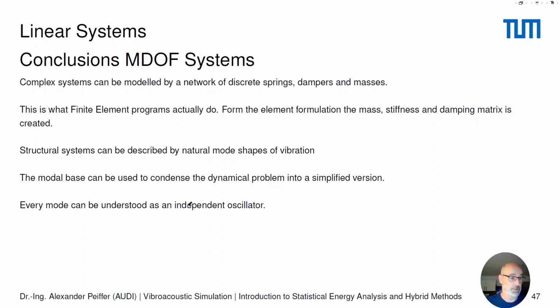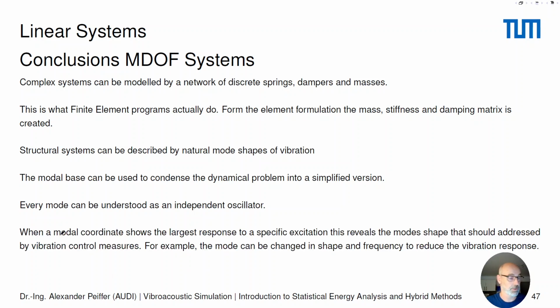Every mode can be understood as an independent oscillator. And what is also important, a hint for practical things: if you look at a problem in modal coordinates and you see that one specific mode is causing the biggest vibration, the biggest displacement, this is exactly the mode that you have to take care of.